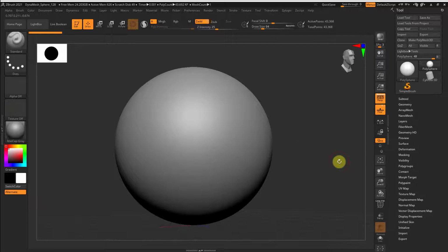To make this a little bit easier, what I would recommend is over here on the right-hand side, right now we have this orange, which signifies that this rotate on all axes is turned on. Directly underneath that we have this rotate on y-axis. So I'm going to click on that, and now it's going to kind of just make things a little less loose. It's going to more easily lock to rotate from side to side. I can still go underneath it on top, but just so you know, I would recommend having this turned on.